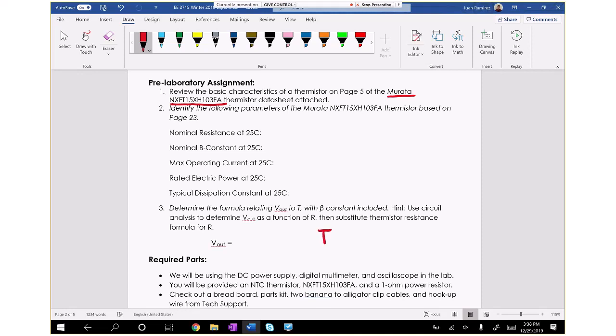So essentially this is the flow of what's happening. The thermistor has a temperature. That temperature is due to the physical environment it's in. So in our case, we're actually going to have it make physical contact with a warm resistor, some other power resistor, we'll call it the heat source. And so our thermistor will reach that temperature. Based on that temperature, it'll have a resistance.